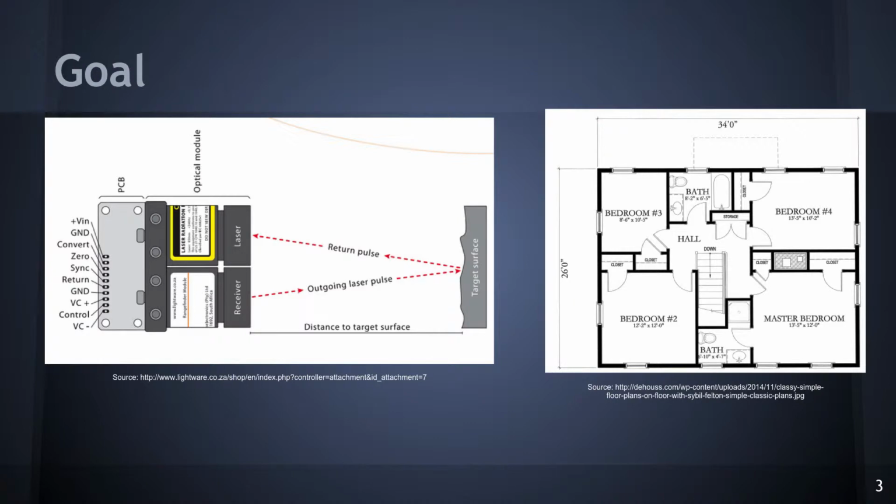The way that the LiDAR sensor calculates distance is by measuring the time of flight of a laser, which it emitted from one lens, and then the amount of time it takes for it to reflect from a surface and back at the desired distance. The time of flight of the laser is directly proportional to the distance away from the object.